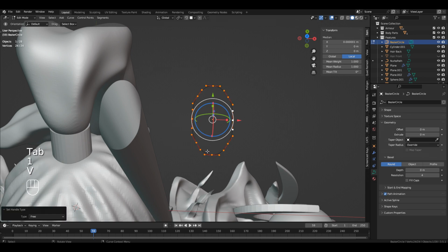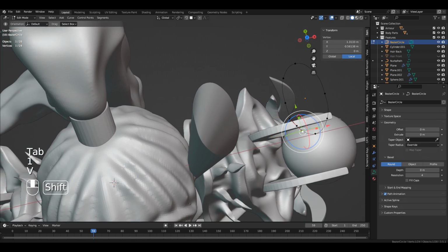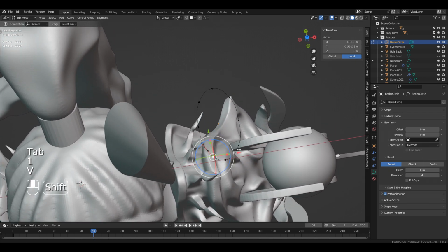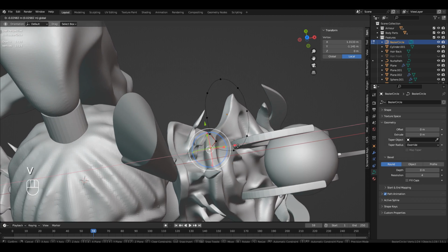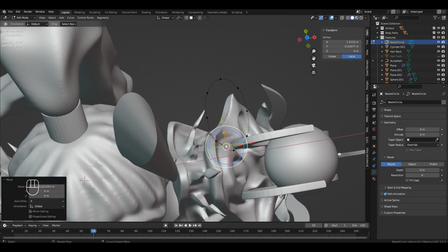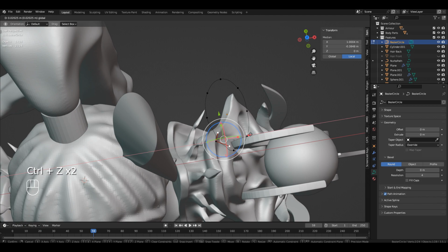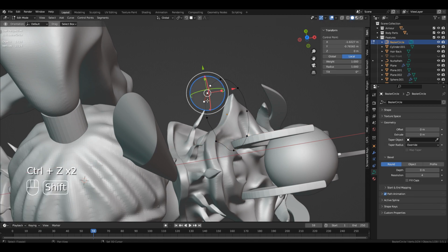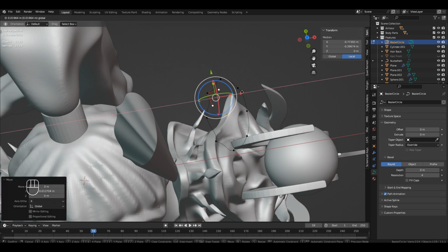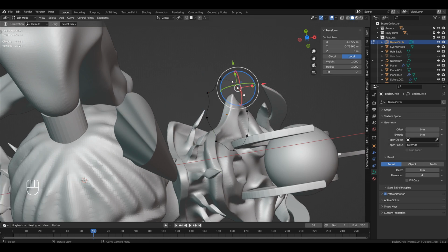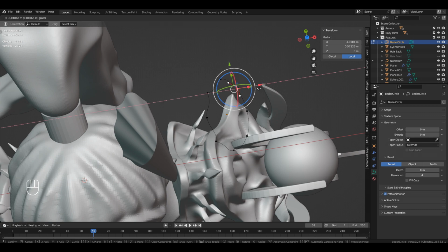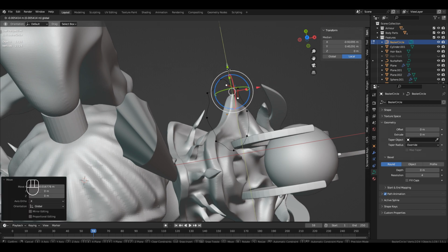So when we select it all, we want to press V and then go to free. What this does is it will make all the handles on these little vertexes free to move. And as you can see, when you move these handles, it changes and deforms the shape on the left there. So that means you can create the hair-like style where it waves in and out, and you can be very creative and do all sorts of designs like this.